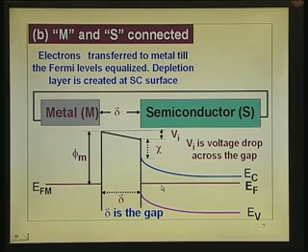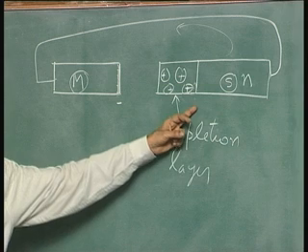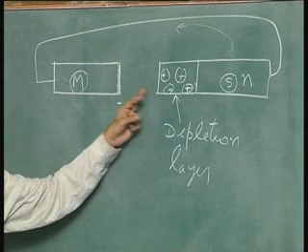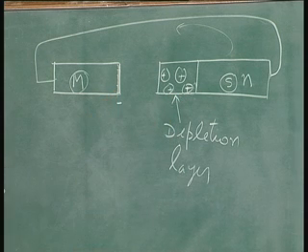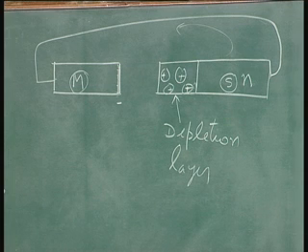The whole thing is because now the energy band diagram has tilted with this side positive and that side negative. Wherever the band bending is there, there is potential change. So there is potential change from this end to that end. This is plus and this is minus. So the charges which originate over this region, they terminate here. You can just see this here.